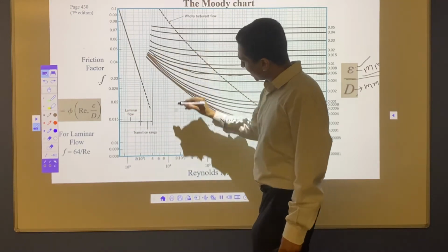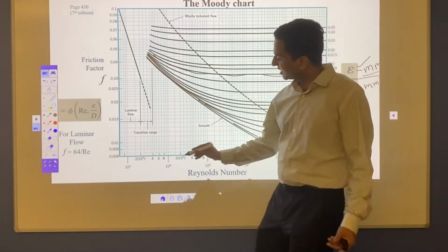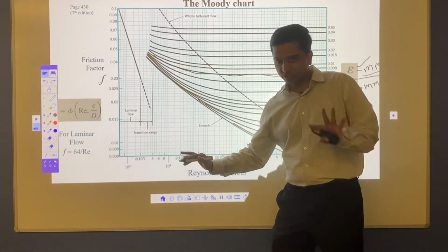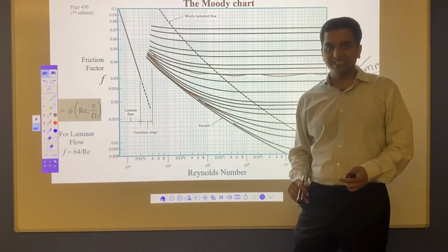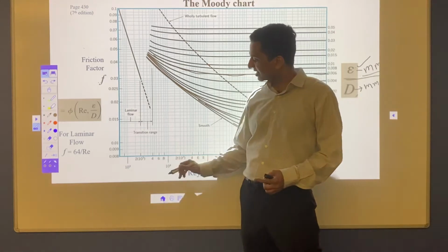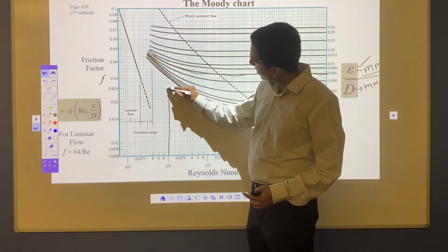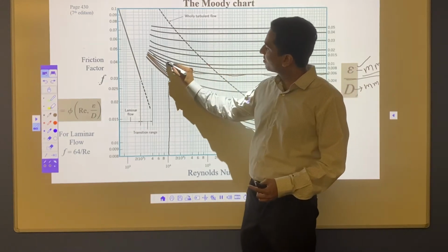And then let's say your Reynolds number is 10,000. All you have to do is draw a vertical from 10,000, so 10 to the power 4. Four zeros mean 10,000, five zeros mean 100,000, six zeros mean 1 million. Four zeros is 10,000. I'm going to draw a vertical from here like this, and wherever it meets that black line from 0.006, I'm going to mark a point.